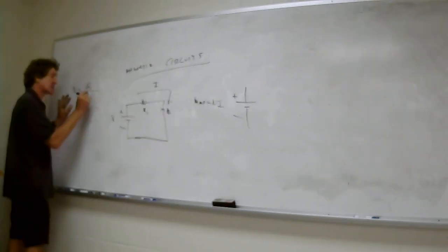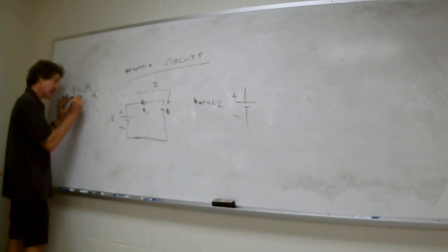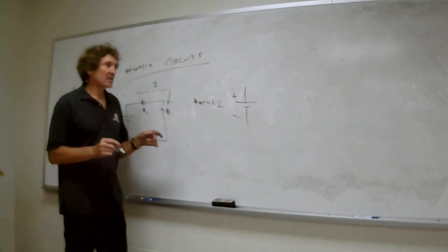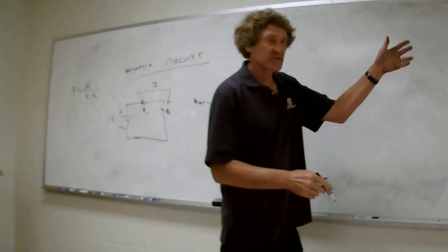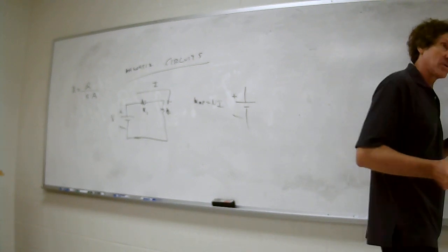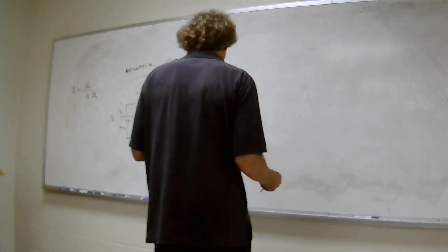Next, remember over here, if you wanted the resistance of a long bar, resistance was what? Length over cross-sectional area divided by sigma. Do you all remember that from resistance class? Over here, if we just have this, I'm going to say that the total length of this thing is really equal to 4A. It goes this way, this way, this way, and this way, all of length A. 4A is the total length.